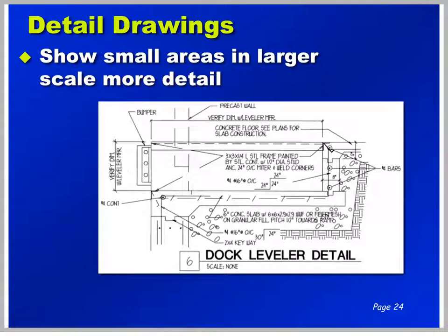Note, there may be some additional shop drawings from the manufacturer that you have to use to build this particular detail. Also note that as we've been looking through these drawings, we start off with plans, we have some elevations, we showed some building sections. The building sections took you to some additional details. So notice how we're going from the overall into the detail.